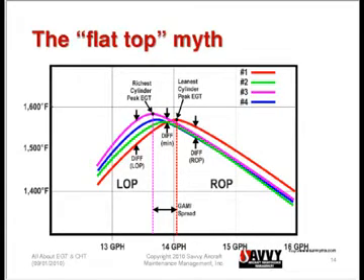In real engines, the mixture distribution is always imperfect, and so the cylinders never reach peak EGT at exactly the same mixture. But our objective is to get them to reach peak EGT as close to the same mixture as we can. And the difference in fuel flow between where the richest cylinder peaks and where the leanest cylinder peaks is what's called a GAMI spread.